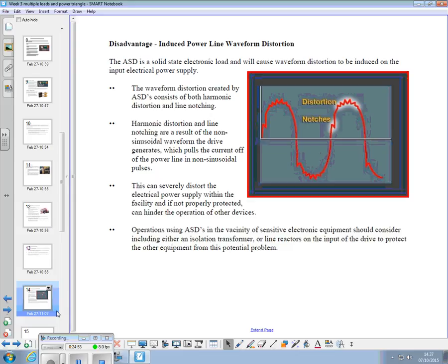Inverters are also used if you have solar panels on your house. What you've got there is an inverter, but you don't need the rectifier bit because you're getting DC anyway. Then they take that DC and invert it and create the sine wave so you can put that electricity back on the grid effectively with an in-feed tariff. So those inverters have to be very specific about the filtration of their output so that they don't output non-sinusoidal waveforms on our national grid. They're a specialist design for that application as opposed to the motor application that we're talking about.